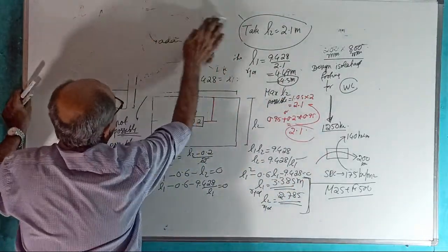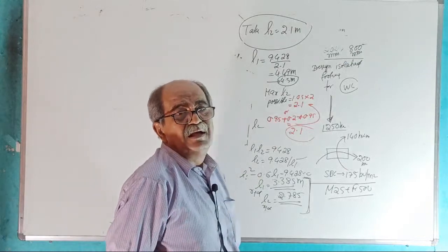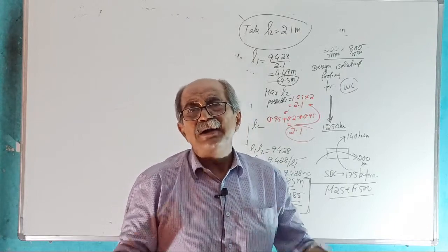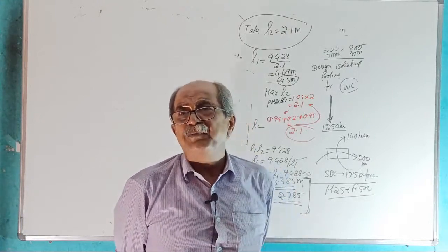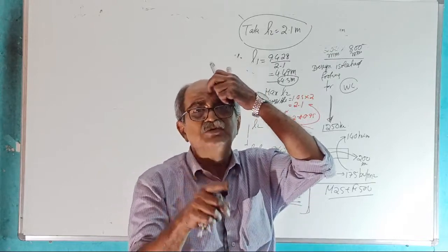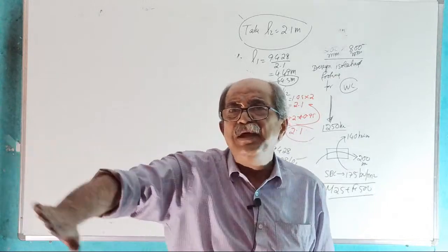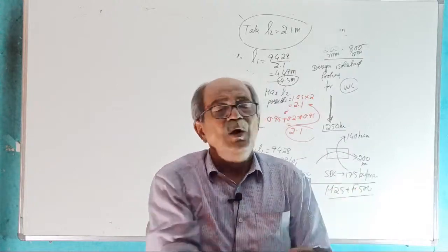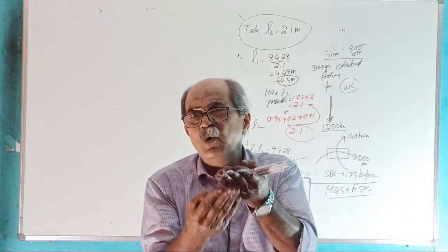Therefore, remember, make a note. Now, what is the problem? The problem is that this footing's projections are not equal, therefore it is not economical, but helpless. We do not want eccentric column. So people in the practical field call this what footing? No doubt concentric only. When one side is too long and the other is short, one side heavy bending will come, the other side less bending will come. Last time it was balanced bending. Once heavy bending comes, depth required is more, shear is more critical. Helpless, we can give more depth and more steel.